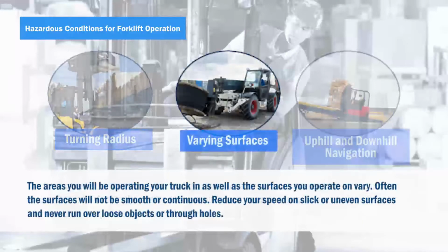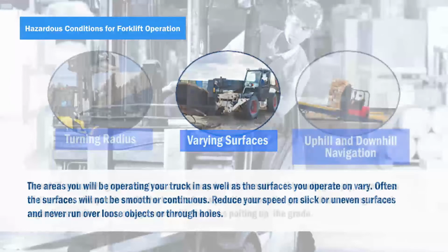Varying surfaces. The area you will be operating your truck in, as well as the surfaces you operate on, vary. Often, the surfaces will not be smooth or continuous. Reduce your speed on slick or uneven surfaces and never run over loose objects or through holes.